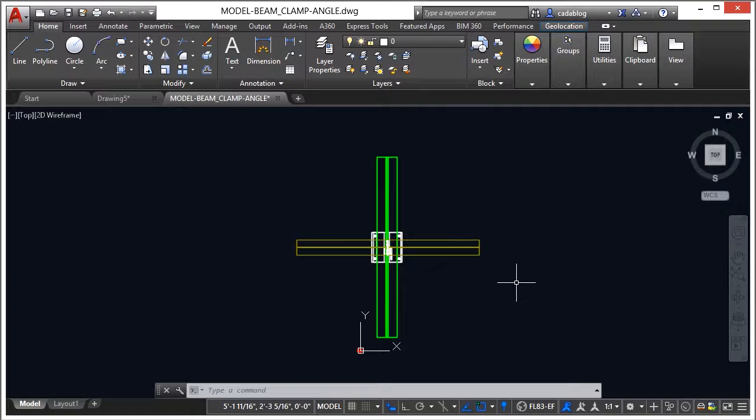Go to Autodesk's website, check for compatibility. It will list the different machines and cards that they have tested. Make sure you have the right one. Go to your hardware acceleration. You can turn it on. Right now mine's turned off. I know because in the status bar here, it says the hardware acceleration is turned off. It looks like this little dial.